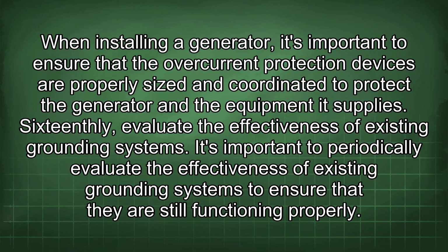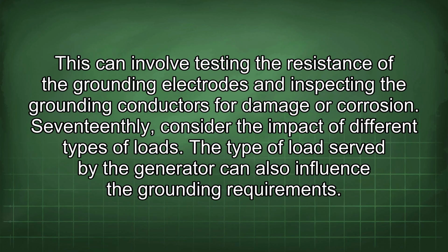16thly, evaluate the effectiveness of existing grounding systems. It's important to periodically evaluate the effectiveness of existing grounding systems to ensure that they are still functioning properly. This can involve testing the resistance of the grounding electrodes and inspecting the grounding conductors for damage or corrosion.